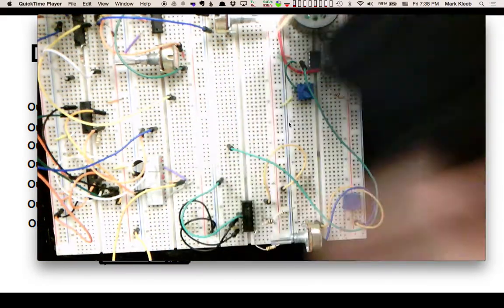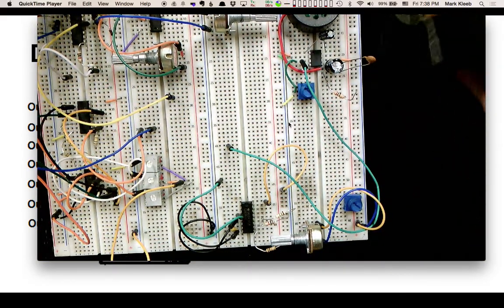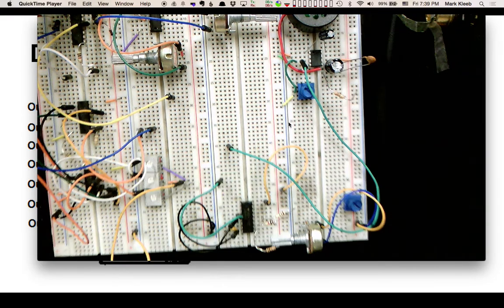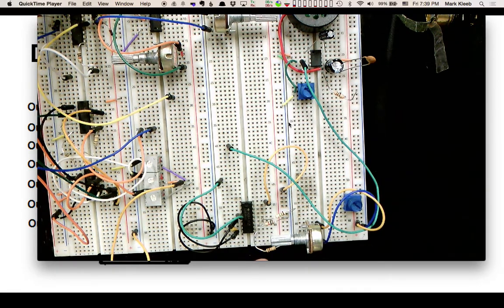how this goes together. And so if you give 0 volts to the VCO, you'll just output nothing? It does output a very low voltage, and I could probably manipulate these resistors to make that inaudible, but because it's 0 volts, you're still going to get a little bit of a sound on the output.